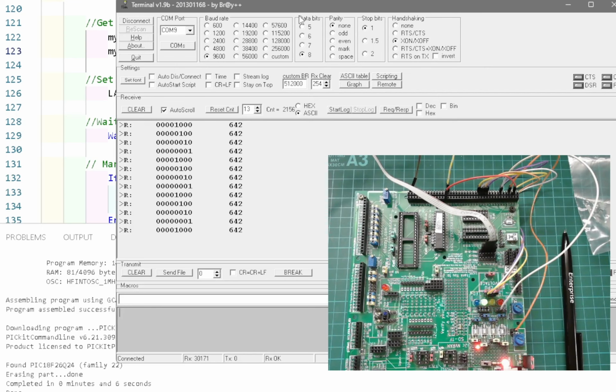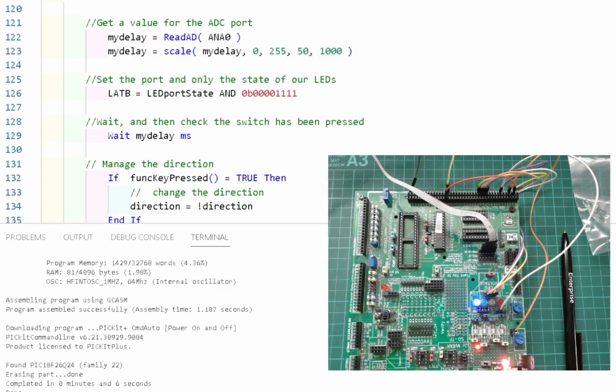I'm using 9,600 baud. I think I tested this chip the other day to 350,000 bits per second. It is fantastically quick, okay? You don't need to stress this thing out. Now, if you change the frequency of the chip, nothing changes in terms of the USART because the compiler recalculates all the settings. Let's just do that in our compiler.